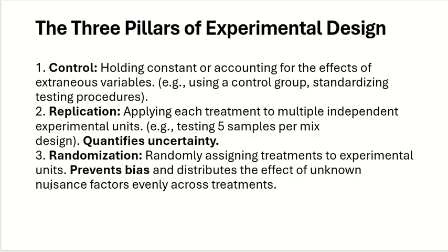So it may mean you apply a method which will affect all the samples equally. Get my point? It's not that I will put admixture randomly. It means I'll put admixture in every second sample. So I have a first sample which is control, and a second sample which is with the admixture. If these two samples are cast together, whatever the problem in them, the problem is the same. Then I will do the third and the fourth, and the fifth and the sixth.